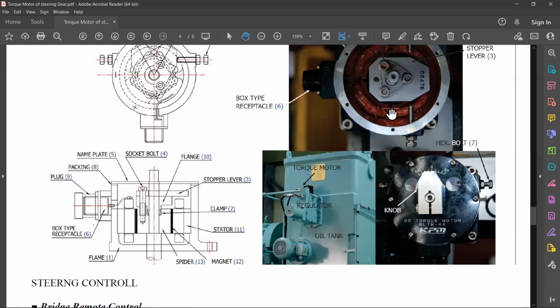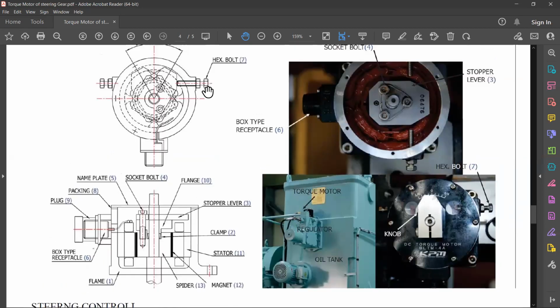Okay. The DC coil motor will keep on energized. And see, there is a clamp and everything. In the de-energized condition, it releases it. In the energized condition, it locks the entire shaft in one position. Once the current is stopped, it will stop in that position only. So you have to do that inside this.